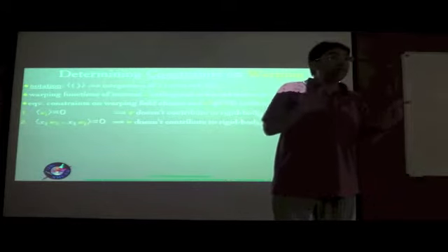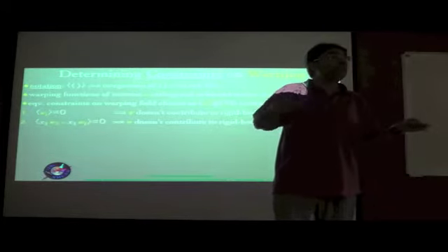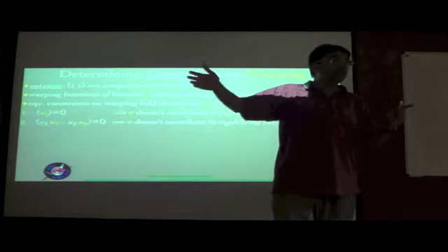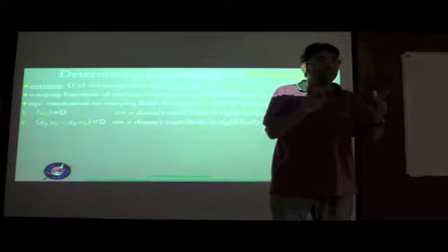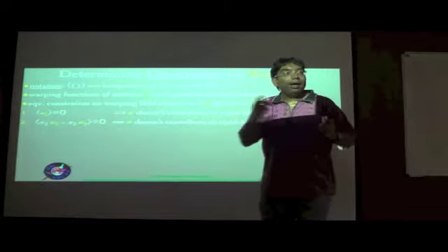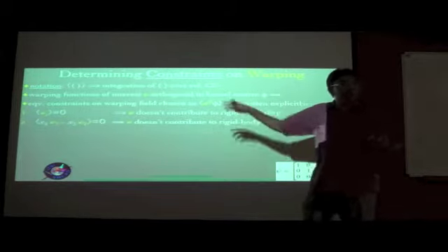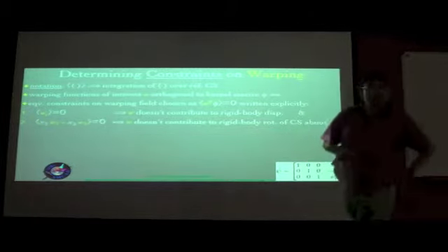In fact, we will see that the simplest case would be to choose, let's say, the centroid, and you would see the relationship between the 1D displacements small u and the 3D displacements big U, which are functions of x1, x2, x3. We will see how the constraints affect it and how the choice of the reference axis also affects it. This choice is independent of the choice of the reference axis, but as a combination, the choice of constraint and the choice of the reference axis together affect the meanings of the 1D variables.